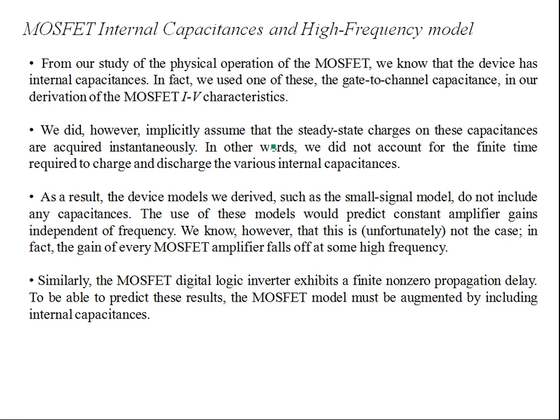Before we develop the circuits including those capacitances in the small signal model of the MOSFET, let's first discuss the MOSFET internal capacitances, and then we shall develop a high frequency model with these capacitances. From our study of the physical operation of the MOSFET, if you recall, we know that this device has internal capacitances. In fact, we used one of these, the gate to channel capacitance, in our derivation of the MOSFET I-V characteristics.